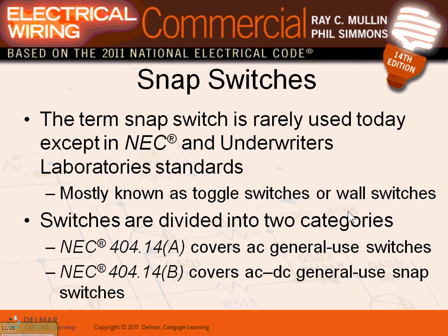Snap switches, you guys deal with snap switches. The toggle switch, you're looking at them right in here. There are AC general use snap switches, or AC/DC. You can use them in AC or DC circuits. Most of the time, the ones that we have are AC snap switches. We're not switching DC in this project.